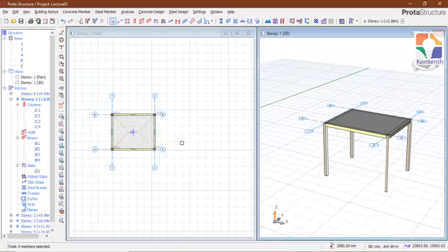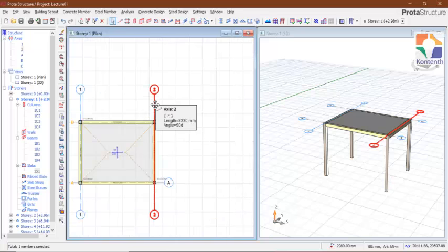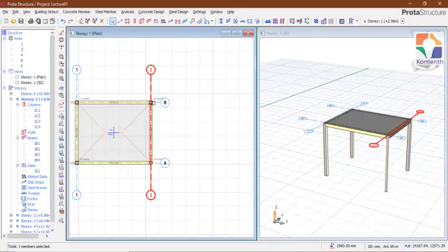Let us say, while you are working, your client says, oh, I've introduced another part, another building. I want you to please extend or make some alteration. Let's say we want to have another building here, which means we want to have another slab or a set of columns and beams again. So there is something we call offset axis. Instead of creating a new axis, you can actually offset an existing axis.